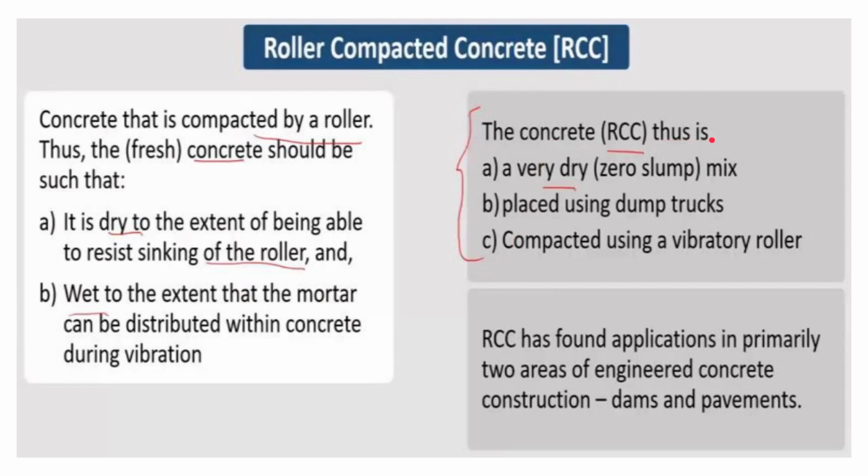RCC is a very dry, zero slump mix. It is placed using dump trucks and compacted using a vibratory roller. So these are the criteria, and basically it has two main construction applications. One is the dam and second is the pavement. So dams and pavements basically use RCC.